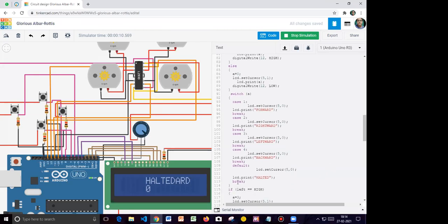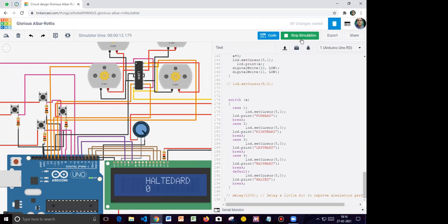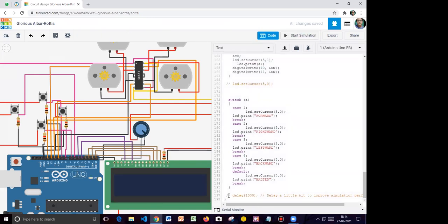Why is it going to default state? When it is pressed constantly, it should set in that particular position and stay there. Why is it going to 0? Add a 1 second delay at the bottom. At the last line, add a 1 second delay. Yep, keep it there.